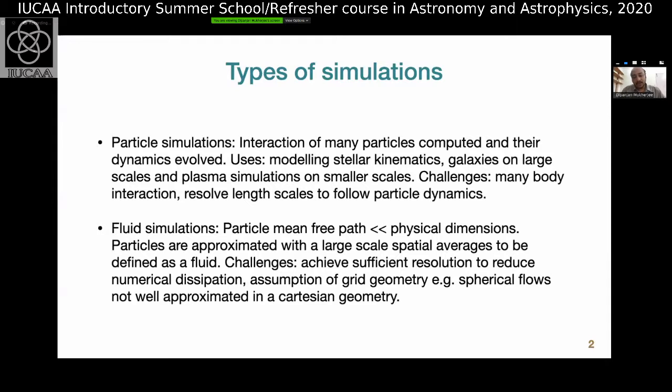So what we do in this fluid simulation is we take again the example of the room. We divide the room into small compartments or small grids and study the evolution of the fluids over this grid. Now, because you are taking a continuous distribution of matter and discretizing it into small sections and then just replacing that small section with an average quantity, you are losing information.